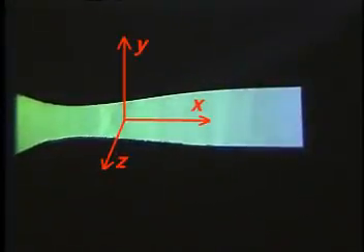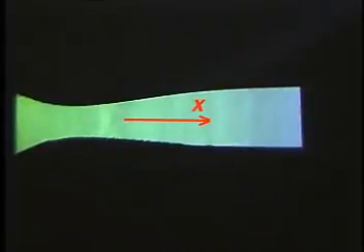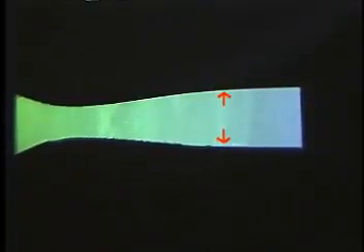Here is supersonic airflow through a converging, diverging Laval nozzle. One-dimensional inviscid theory in the x direction is sufficient to describe this flow, except for the viscous boundary layer at the walls. Here, these are quite thin and can be ignored. However, the flow over this wedge requires a two-dimensional theory in x and y. When the normal shock wave moves back up the nozzle, its interaction with the boundary layers becomes too complicated for any simple theoretical model.